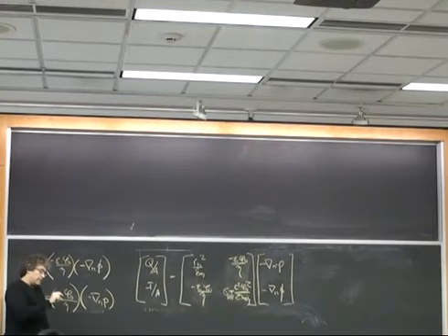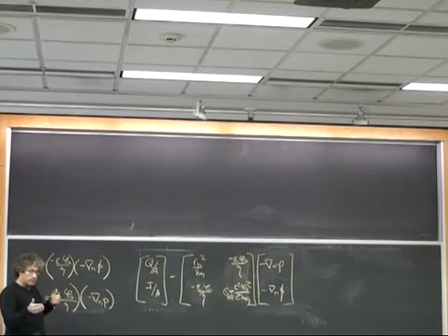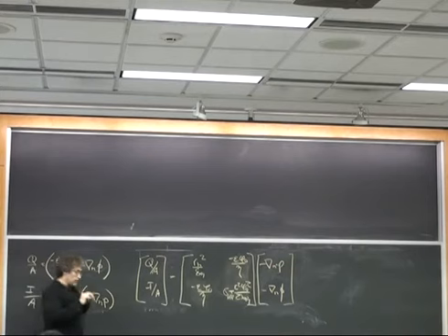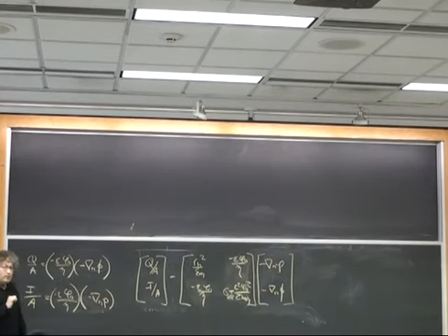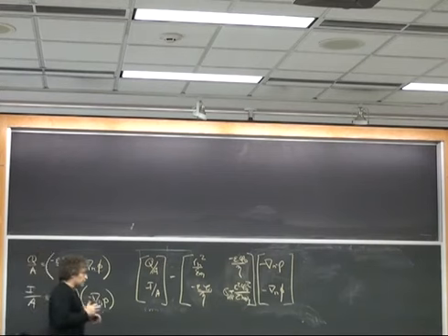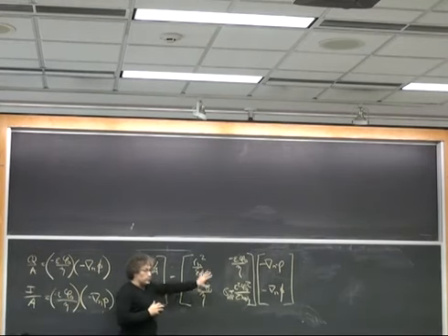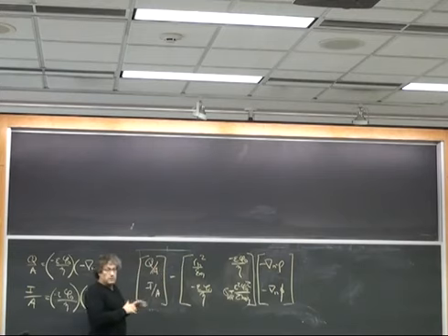So if I have a 50 nanometer deep channel that is 4 millimeters long, the edge effects are relatively easy to ignore, and really all I need to do is keep track of the area average effect. That will tell me all the engineering parameters I need to know. If we make the geometry more complicated, then this formulation will cease to be useful, and we'll just have to solve the transport equations in their full form.